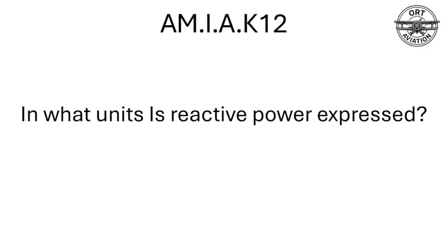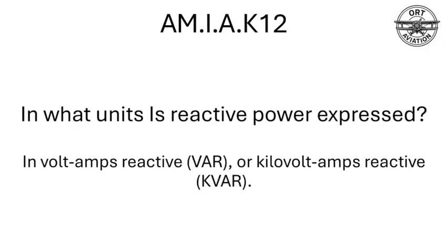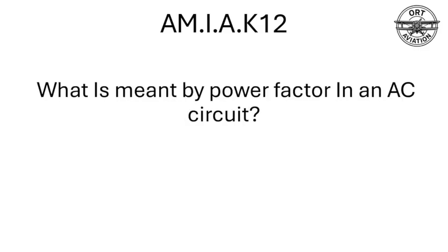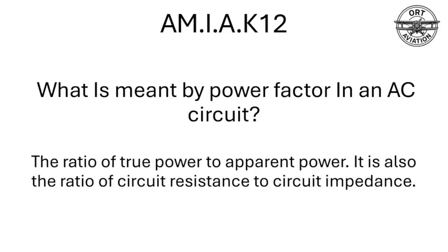In what unit is reactive power expressed? In volt amps reactive, VAR, or kilovolt amps reactive, kVAR. What is meant by power factor in an AC circuit? The ratio of true power to apparent power. It is also the ratio of circuit resistance to circuit impedance.